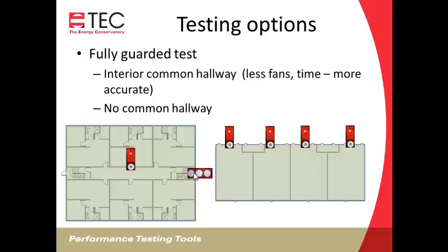And so once you get the entire building up to pressure, you're not concerned about the flow at all through these 3 fans. You're just interested in setting those to cruise at 50, and then you set up a blower door in each unit and measure with respect to the hallway and bring that up to the same pressure. So the same pressure as the rest of the building.